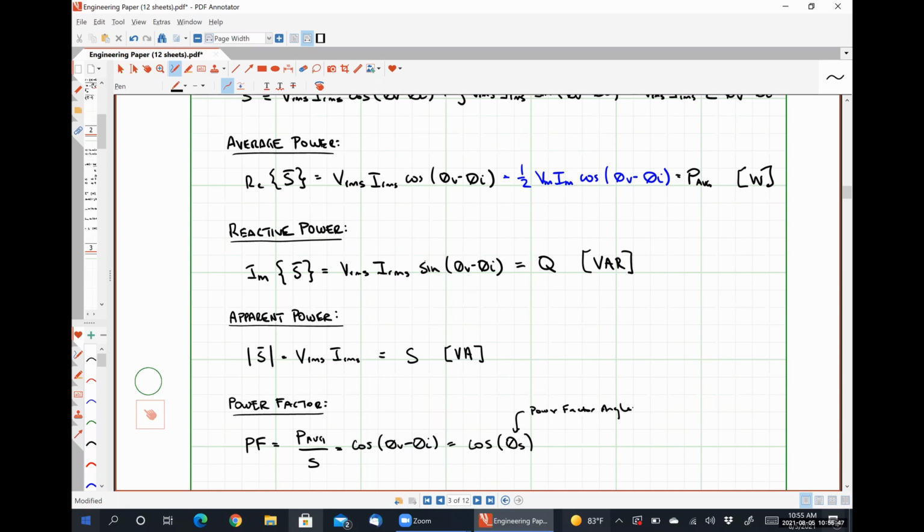Power factor ranges from -1 when a network is supplying apparent power at 100% efficiency to +1 when a network is absorbing apparent power at 100% efficiency. Okay, so when a load operates at a power factor less than a magnitude of 1, it means that the source is being required to generate more than the minimum volt amperes necessary to supply the required average power needs of the load.